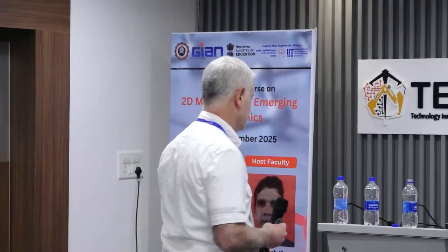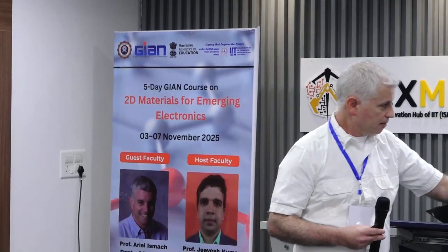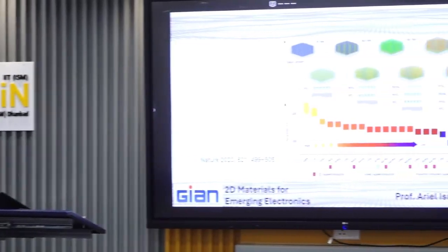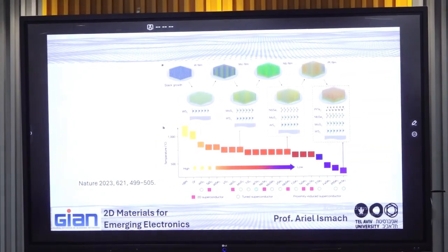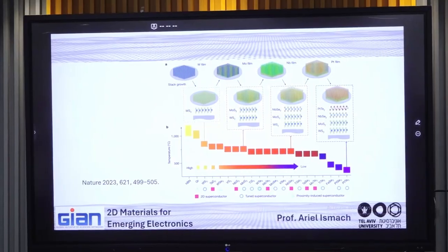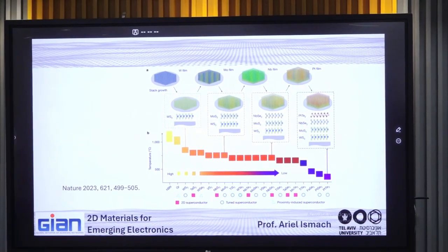And of course, when we grow different materials, we need to take into account the compatibility between the materials, as I showed you before. For example, in one of the cases they showed you here, they designed the process with lowering processing temperature along the way, in order to avoid as much as possible damaging the already grown raw materials.